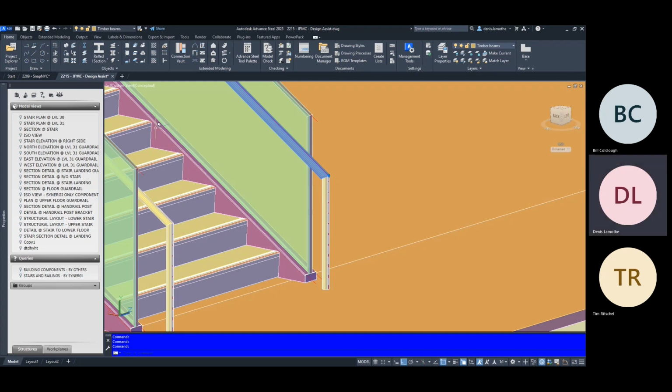If your tread widths are 12 inches, then this point would have to be 12 inches past the nosing line here. And it doesn't need to kick out horizontally after. It could die right into the floor. It could just stop right there in the air if it wants. There's no requirement for a horizontal extension there.